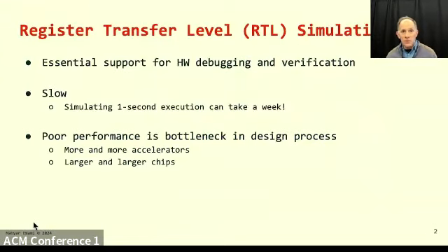Those of you who design hardware know about RTL simulation. That's the way you describe the function of the hardware, typically in a hardware design language like Verilog. And then you run it on a simulator to see whether it works, to do testing, verification, and debugging. The problem is that the simulation is slow. It can take a week to simulate an hour of execution time if you're using a high-speed processor. And this poor performance becomes a bottleneck in your design process.